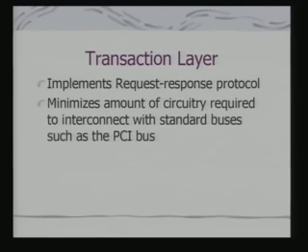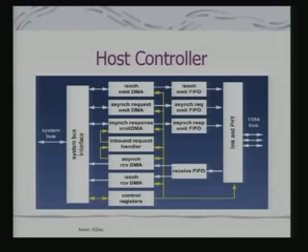And the way it is designed, the basic specification is such that it minimizes the amount of circuitry required to interconnect with standard buses such as the PCI bus, because one of the prime movers of these standards was PC manufacturers, and they would like the PCs to play a role, and it should not be just among the devices. So, the standard is specified such that there is a compatibility with the PCI bus. And your host controller of IEEE 1394 is something like this.